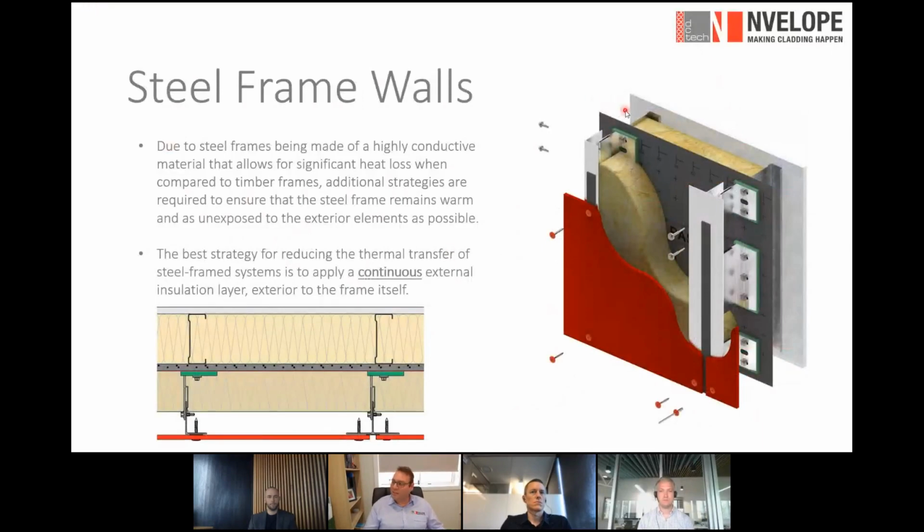As you can see in this image, we have our internal insulation and a vapor permeable membrane, but we've also added exterior insulation. Now this is continuous. And how do we achieve this? We install a framing system like our envelope framing system seen here, where it has a very small footprint touching back to the substructure, allowing for the insulation to be encased around it.